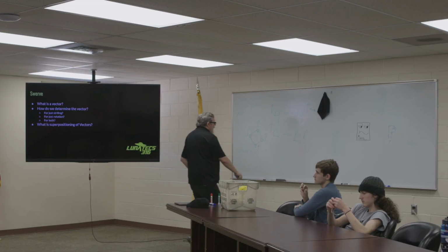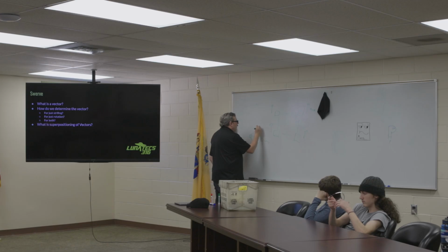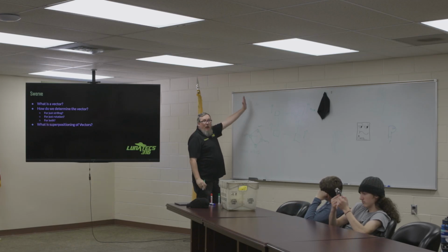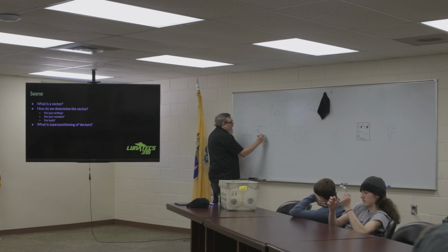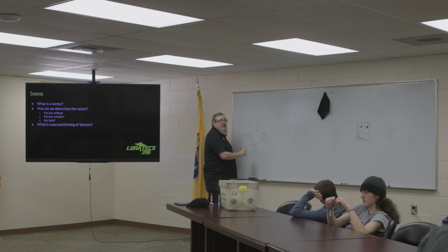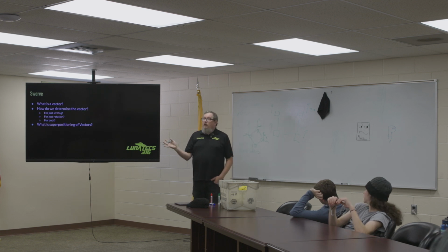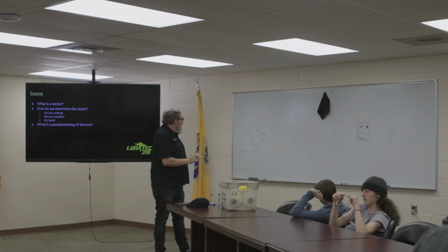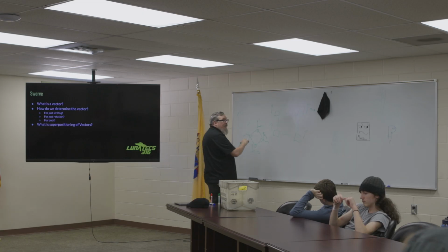So, hypothetically, if my wheels are facing this way, and I want it to go that way with the controller, what is my error? 90 degrees. Gotta turn every wheel 90 degrees. And I use a PID loop to do that, to control how the direction of my wheels face.